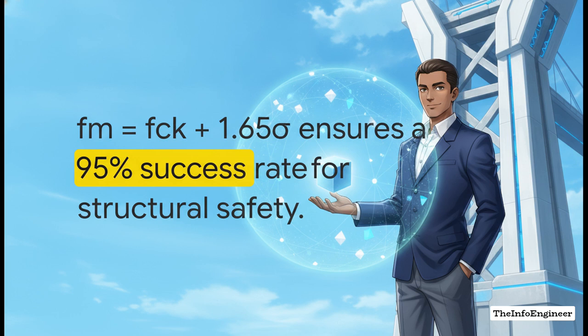As we all know, concrete has inherent variability. So to ensure structural safety, engineers design for target mean strength, that's the fm, that is actually higher than the characteristic strength, fck. By adding 1.65 times the standard deviation, the design mix statistically guarantees a 95% success rate for structural safety. You aren't guessing anymore. You know exactly what load your building can carry.